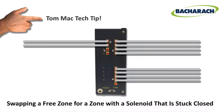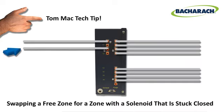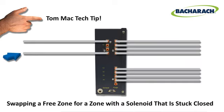Prior to replacement of an entire manifold, consider swapping a free zone for the zone with the stuck solenoid. Assuming an extra zone is available, just be sure to reconfigure the zones appropriately. Note that this option can only be successful if the bad manifold port is stuck closed. For a bad manifold with a port that is stuck open, the entire manifold will need to be replaced.